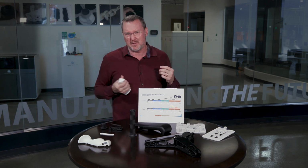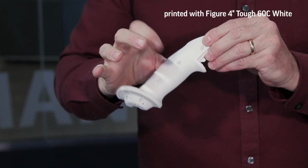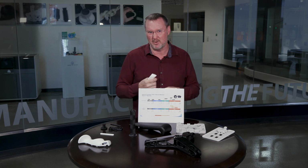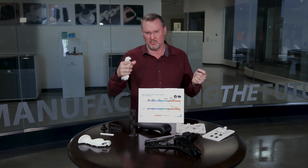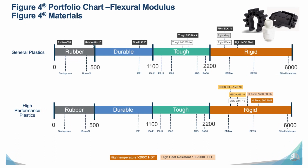Your tough parts are going to be things that are handled a lot. So that's why when we talk about some of your ABS parts, very common injection mold material, if you look at your tough materials, then you're going to see that same kind of toughness that's needed in the repeated loading, and something like handles and grips and something that you can turn and twist that really put a load on over and over again.